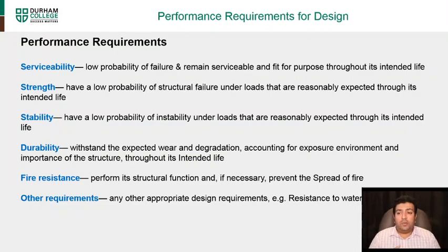Stability: a low probability of instability under loads that are reasonably expected throughout its life. Then you have durability: withstand the expected wear and degradation, accounting for exposure to environment and importance of the structure throughout its life. And then fire resistance: perform its structural function and, if necessary, prevent the spread of fire. So wherever it's required to prevent the spread of fire, we can use this.